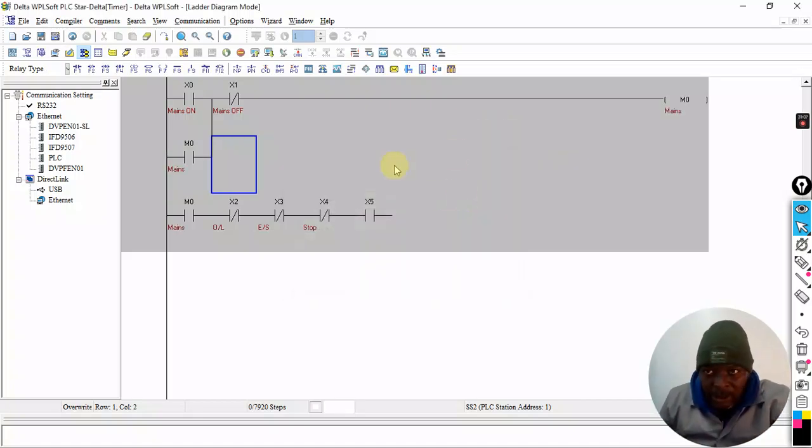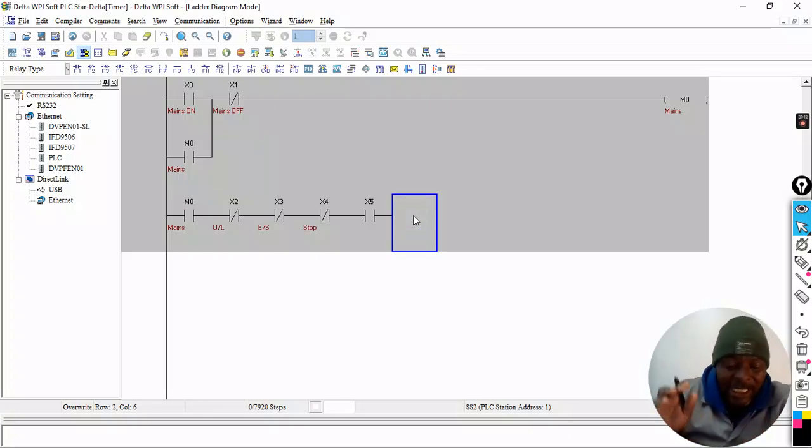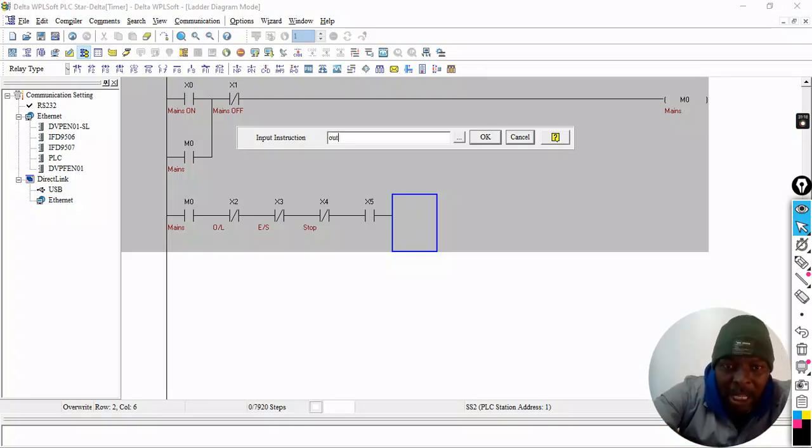Now I want to start M, the main conductor. This is not the mains as in the supply, but this is the main conductor. So what I'll do, I'll say out. I don't need it to be a physical thing, this one. Why? Because I just want it to control the timing only. So I don't need a physical mains conductor in this case. Because the job of the mains in that situation was to hold the circuit 1, and 2, it was also to carry the timer. So in this case here, we don't need that. The PLC can do that within the software.